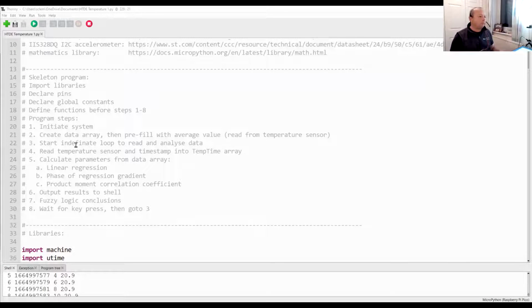So this is my program. I'm just going to run this very quickly. The way I do things is I have an initiation process to start with, where I just blink some lights and I send a hello world message over the UART. So I just know everything's alive and working. And when you're doing debug, it's good to know that the foundation of your debug is actually working before you do anything else. Otherwise, you might be chasing the wrong error.